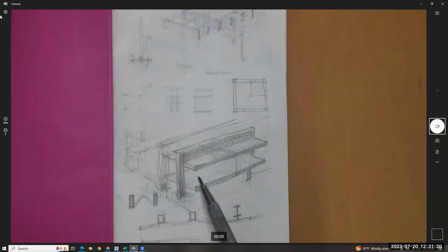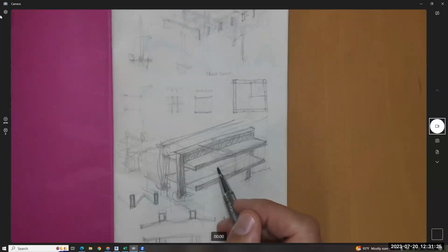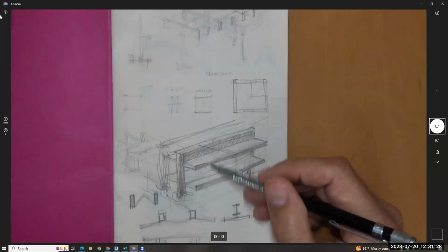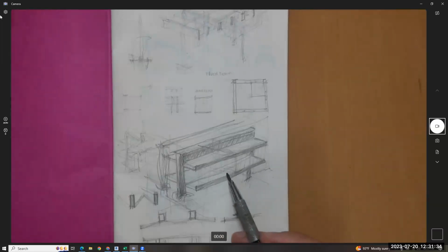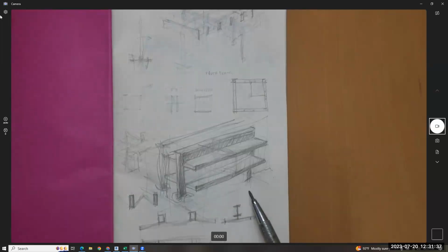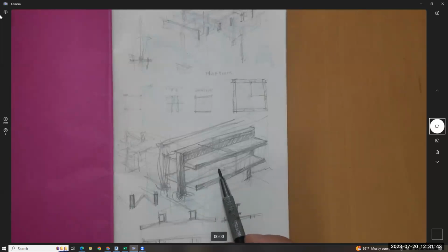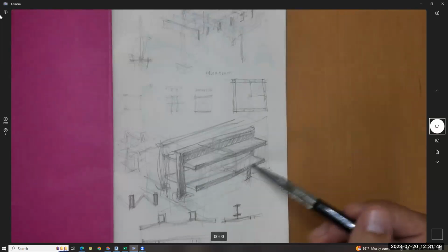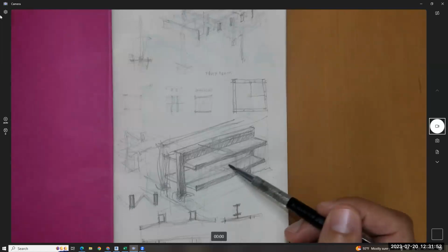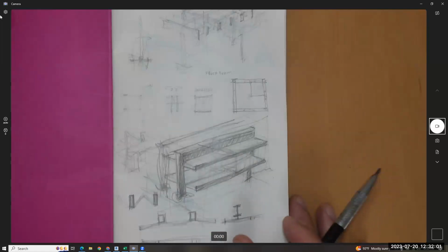What's kind of interesting is that idea that that beam that was crossing at the bottom, right? It had that weird top edge, right? So we think about that, what that's doing is when that has a face here and wind is hitting that, you could almost say that those beams have a little bit of bracing to them. That's kind of what's happening, they're being thickened to resist the force in that plane. So it is a shear diaphragm, but the beams are actually reinforced to resist that horizontal force to transfer it down. So that's what's also really helping in that Z plane. Okay.